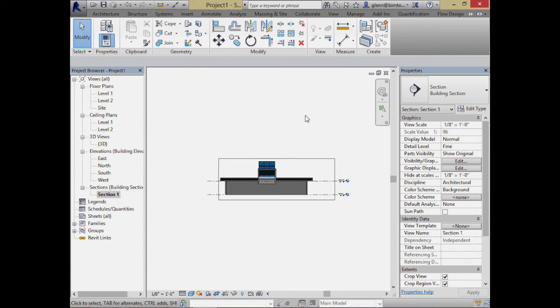For a grid system like that, I'll tend to do that either as a surface that'll break up as a divided surface. Julia and I were talking about something like that a little while ago, about breaking up a surface. We'll show you how to do that. Or you could even do that as a curtain system, because curtain systems have this whole notion of vertical elements, and you can make light frame members to do something like that.